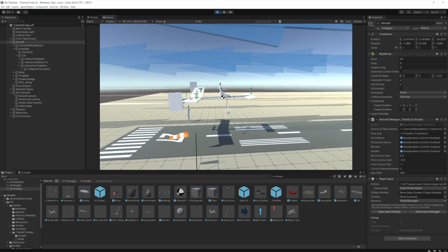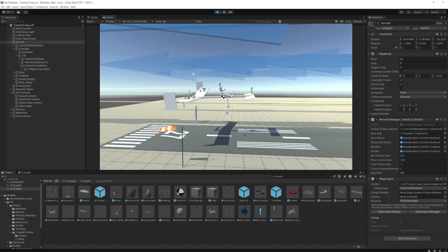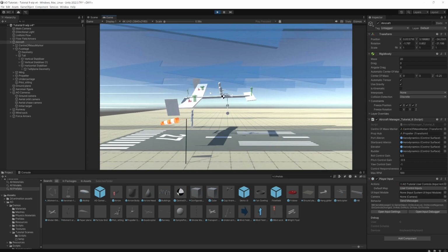Okay, so that's not bad. If that was flying, we've got a bit of lift on each of these wings. It's being balanced out by the lift on the foreplane, but that aircraft would fly. And so I've got some roll control, and I pull back on the stick. We get more lift, so I'll trim at a lower speed. Push down on the stick, you get less lift. Trim at a higher speed or even upside down.